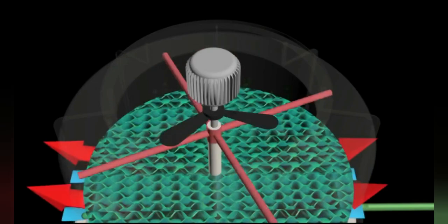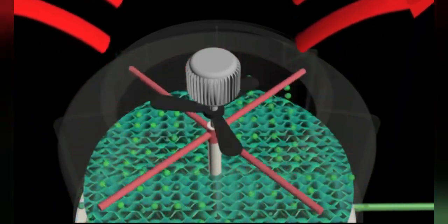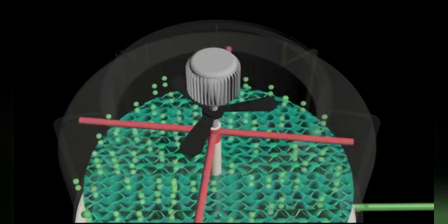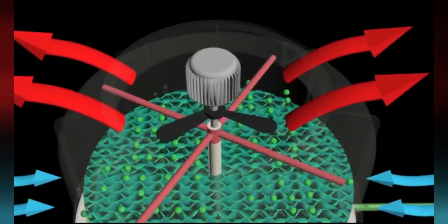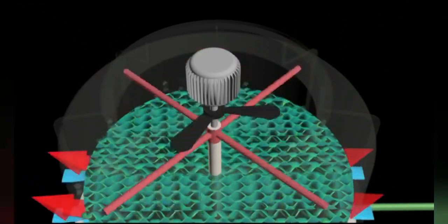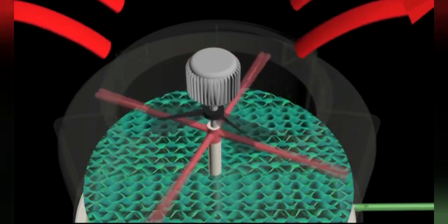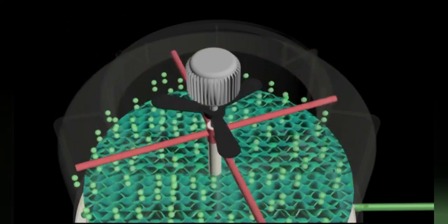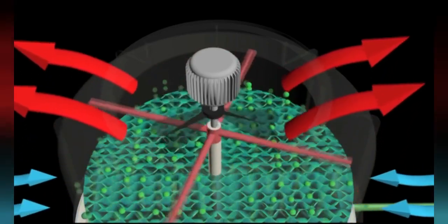This can delay the time so the heat can be absorbed more effectively by the surrounding air passing through the fins. Air through the fins is forced by a rotating fan on the sprinkler blade rotated by the motor. This fan rotates with its gusts upward. This will cause the air to move from the bottom to the top of the cooling tower, opposite to the flow of the condenser water.